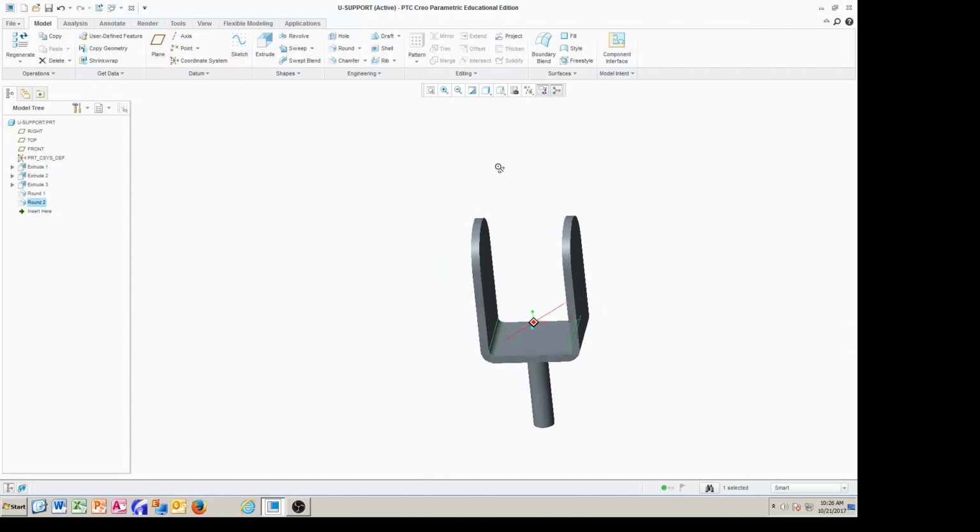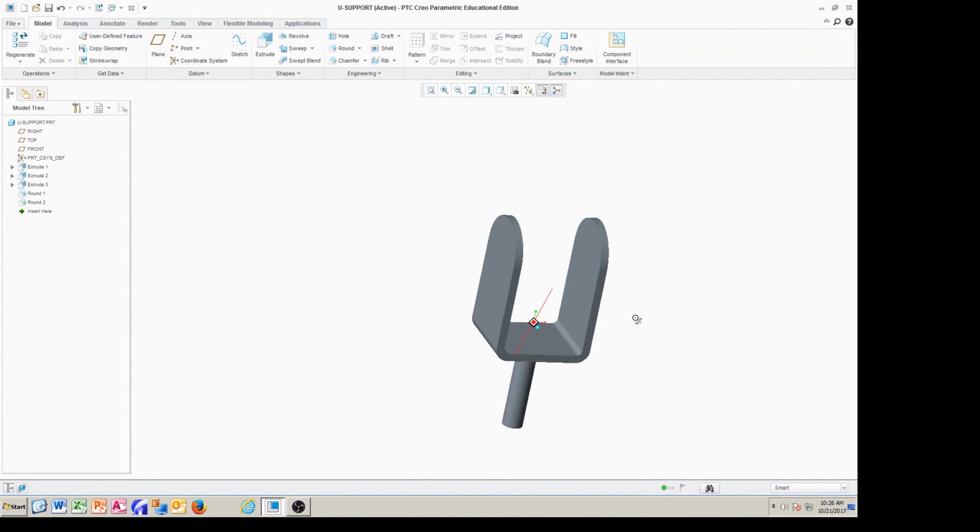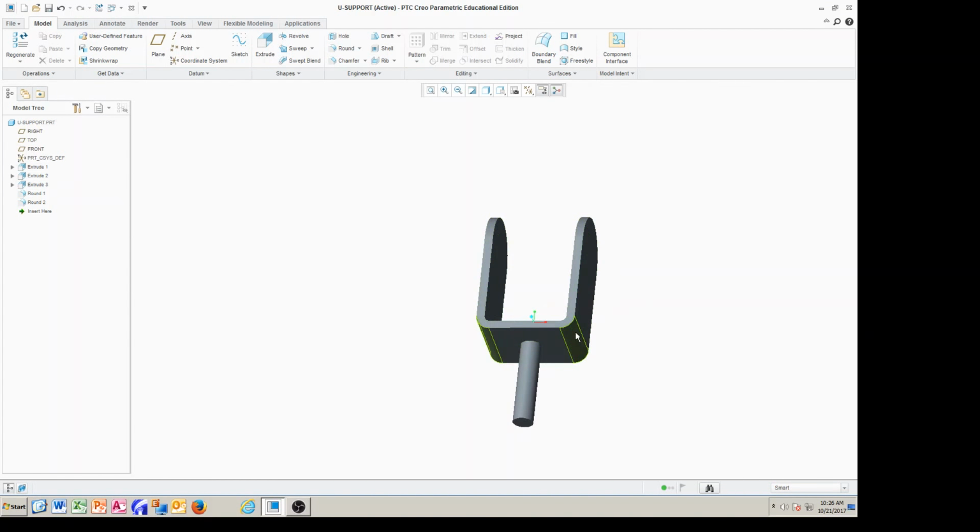So this way it will make this shape stronger. The stiffness of the materials is important when you use it in an application, so you don't want this to break. So that's why we put a round, a little bit larger radius outside and a smaller radius inside.